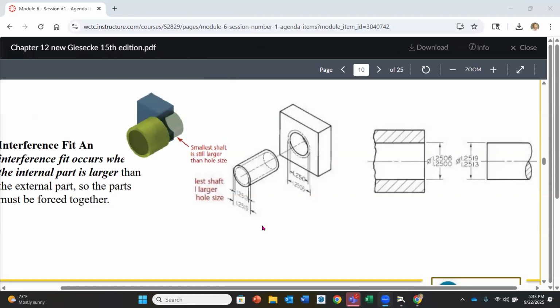Now, when I was at Hyson, we had very high speed packaging equipment. When I say high speed, this was like the winders for toilet paper, paper toweling. You can imagine how incredibly fast that those go. They do, and you need them to last a long time. So we were super precise on those because we wanted those to be properly lifed and all that kind of stuff. Well, the application of a lawn tractor, just going at a very low speed, not on the highway, isn't as critical. So they were just pressing, and I'm like, oh my gosh, you're pressing in bearings. And they're like, it's the application.